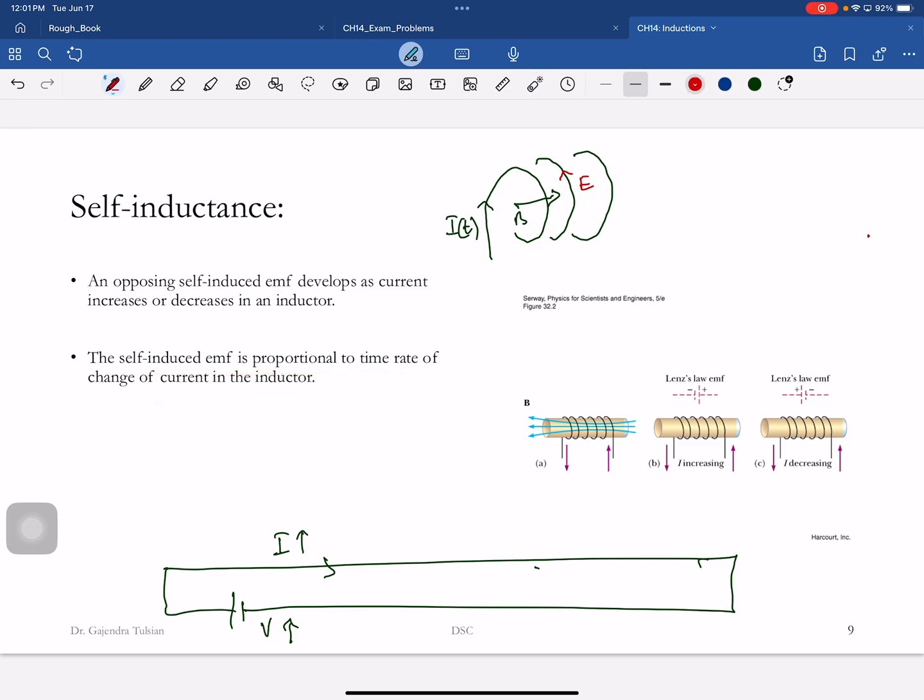Okay. So if the wire were straight, I close the switch at time t equal to 0, the current will go from 0 to its steady state value. Okay. If I take this wire and wind it up into a thing like that, now the current will rise exponentially. It'll still get to the same final value, but the behavior of that coil has changed.